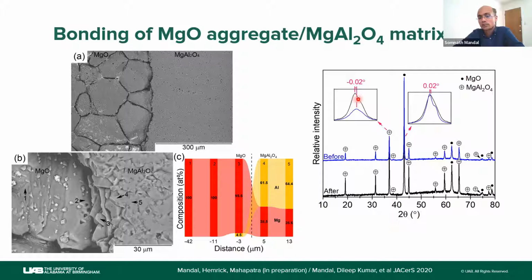This is because this lab grade spinel was calcined at 1400 degrees C, and when we did XRD, the spinel crystals were just formed, so properly formed crystals were not there. But when you sintered this entire thing at 1600 degrees C for 5 hours, the 200 degrees Celsius higher temperature and then longer firing time gave the time for the spinel crystals to form properly, and that is why you see this increase in the intensity of the spinel peak.